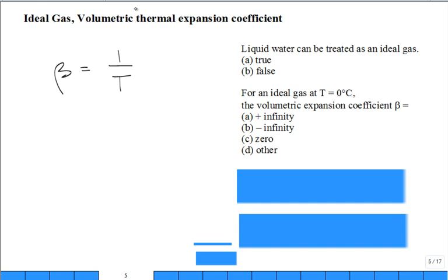So somebody said, well, we derived that result knowing that we started with rho for an ideal gas is P divided by RT. This equation is the starting point, true? But tell me a little bit about this T and this P that students in Thermo 1 may make a mistake on, but you would never. Absolute, that's what we're looking for. Thank you very much. It needs to be an absolute pressure. Don't put in gauge pressure.